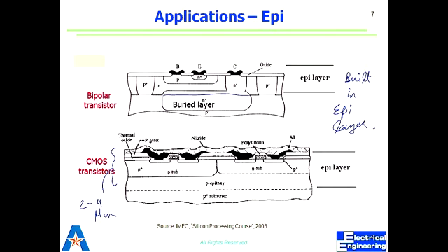You want the well to be heavily doped also, in this case, so this is N plus. Now your devices are built up within that. When you have the reversal at this point, you have the channel formation happening there with the P-type substrate with the holes. But the purpose of the buried layer is to decrease the collector resistance, right?